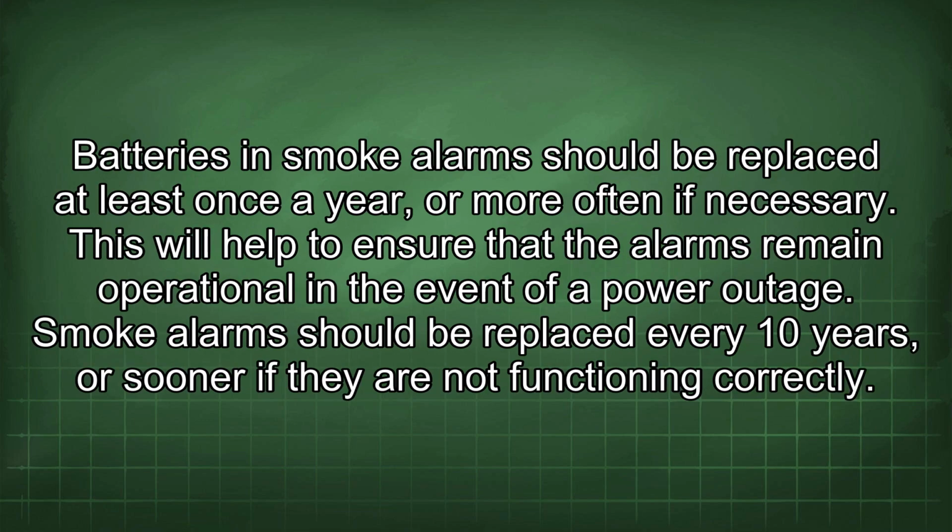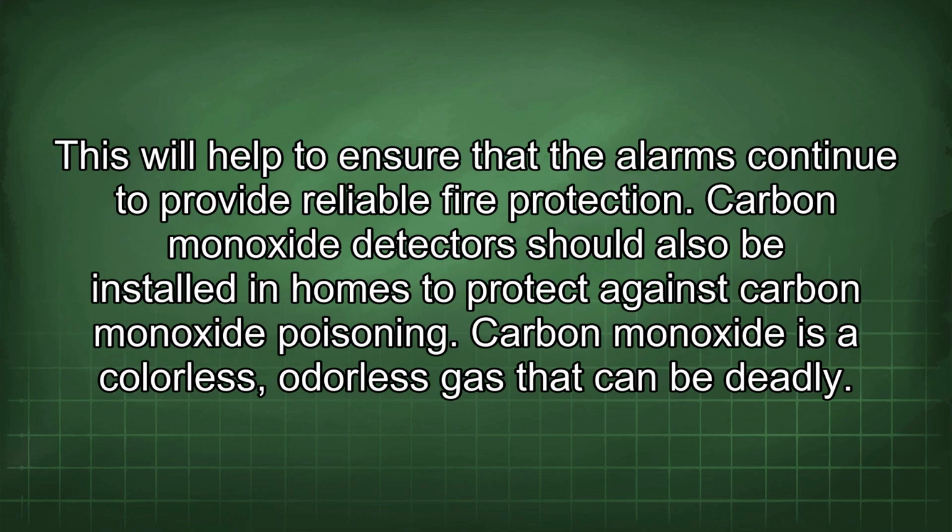Batteries in smoke alarms should be replaced at least once a year, or more often if necessary. This will help to ensure that the alarms remain operational in the event of a power outage. Smoke alarms should be replaced every 10 years or sooner if they are not functioning correctly. This will help to ensure that the alarms continue to provide reliable fire protection.